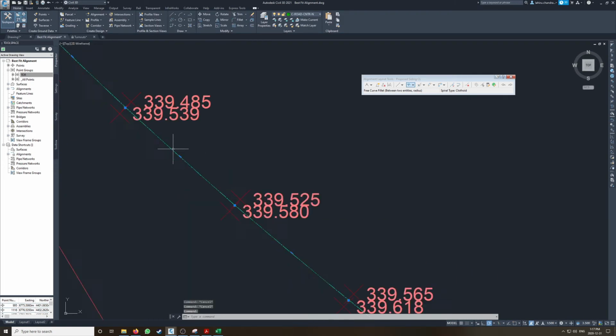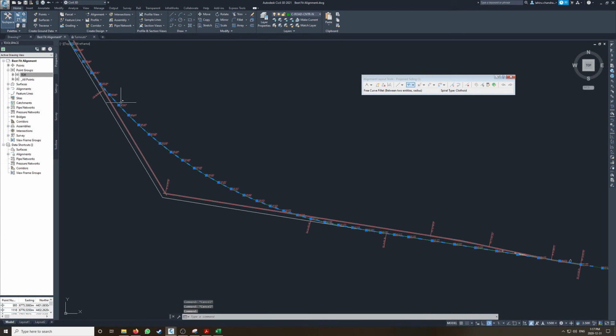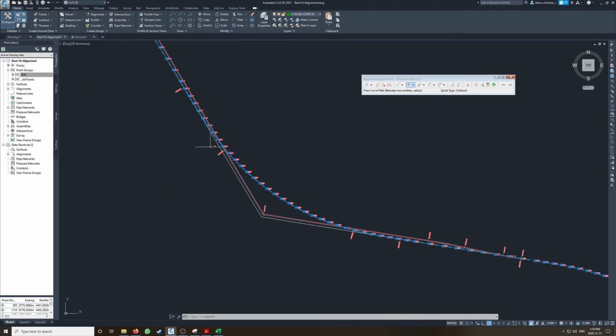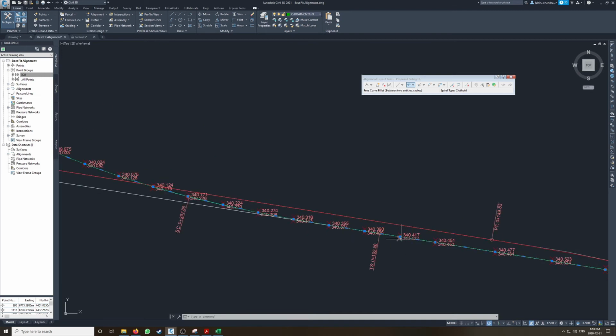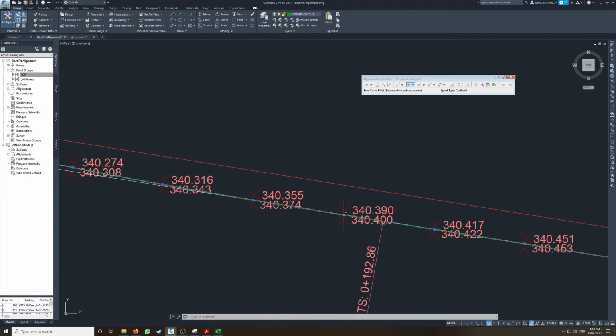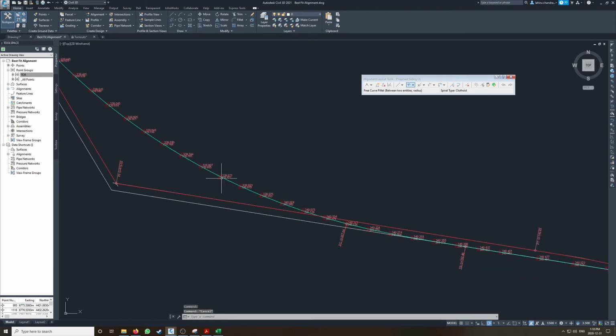So the green line here is our center line from survey. You can get that from your surveyors, or if you don't have it, you'll have to create a new polyline which uses the center points between the 2 points. So we want to offset that 15 feet plus 2 inches per degree of curve.